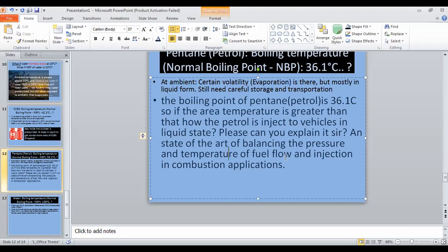So more surface area for combustion and maybe finer particles than the carburetor effect. With a carburetor, you have the vapor form only. But in injection, you have more turbulence and more fine particles, and there can be an enhanced combustion effect.